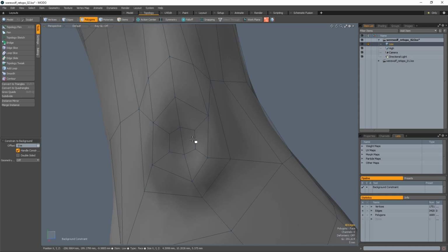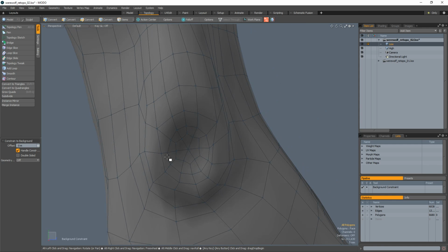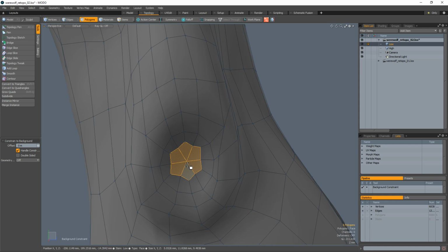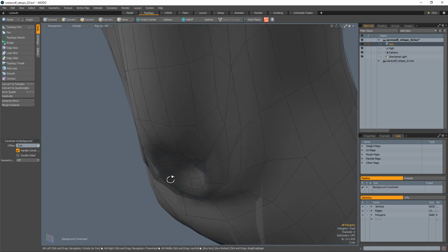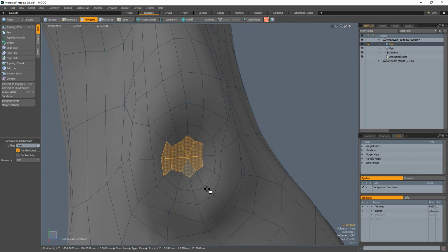So here's what it looks like when it starts off as an n-gon, and then I subdivide it. It turns into this shape that has a bunch of quads in here, which, having quads is good, but the problem is that when these quads, or when a similar layout of quads is imported into an engine, they'll be converted into triangles, just like any other polygon would be, but it's difficult to predict how they're going to triangulate.